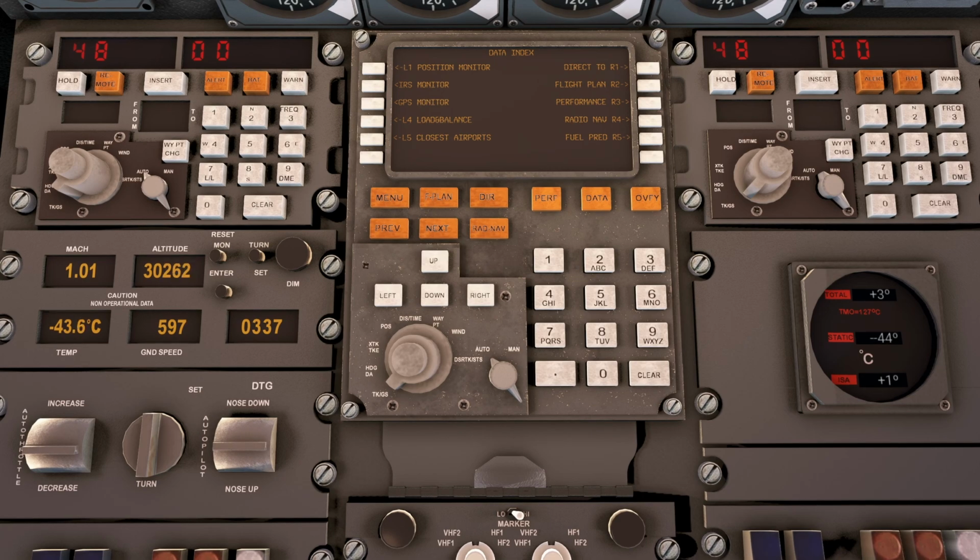If we approach that temperature, we have to immediately climb. So the rest of the flight is going to be a little bit of climb, 200 feet. Let it establish, temperature comes up, climb again. So that is supersonic flight in Concorde.